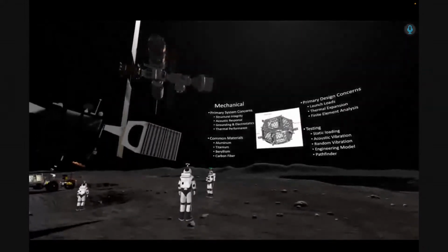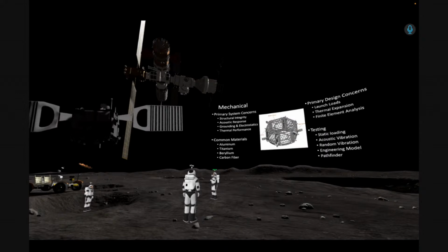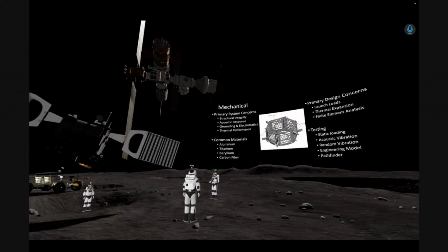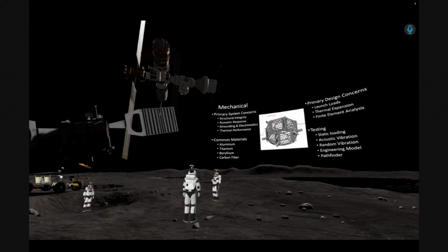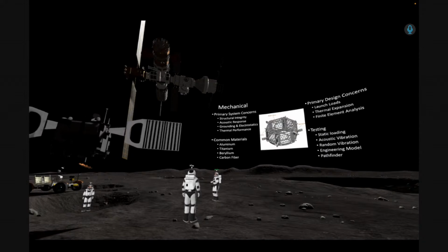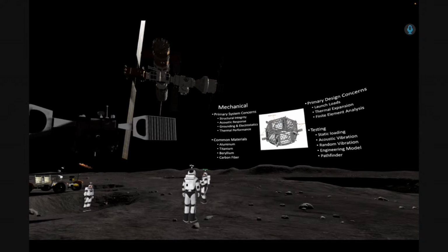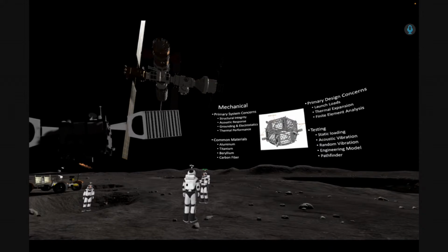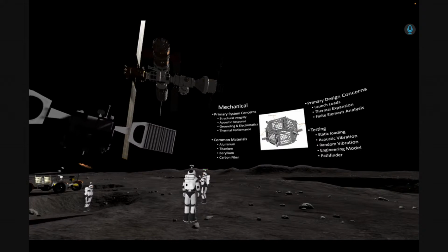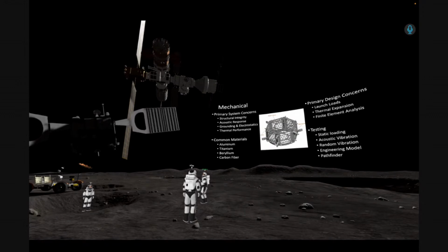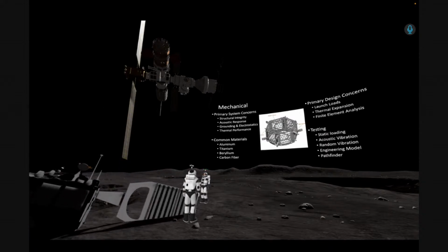So coming back to the topic, this amazing satellite that you're building will be put into a rocket, and rockets are not the most delicate thing. You have seen the launches, and the launches are crazy. They move a lot. They put your satellite into very harsh conditions that are not the same conditions in which the satellite is going to be in space. It's going to be something totally different. It's going to have a vibration like crazy. So this can be the vibration testing, but you can also have the acoustic testing. In the acoustic testing, the satellite is exposed to something worse than the loudest concert you might ever have had in your life. So you put the satellite inside these anechoic chambers.